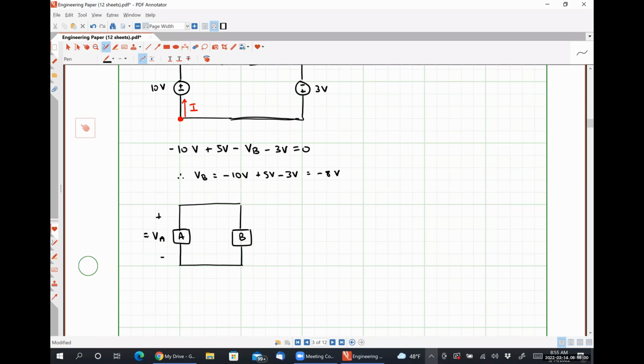If the voltage drop over element A is, let's say, 3 volts, what does the voltage drop across element B have to be? Assuming that VA and VB have the same polarity, 3 volts, right? So Kirchhoff's voltage law tells us that when elements are connected in parallel, they have to share the same voltage.